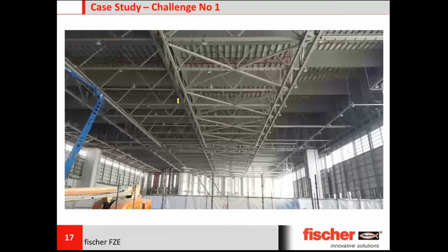We looked for ceiling and support locations from where we can drop our threaded rod to support the firefighting pipes, but we realized there is no concrete. There are some beams, I-beams and box beams, but they were all really far. And to make it worse, the pipe was not coming directly below these I-beams or box sections.